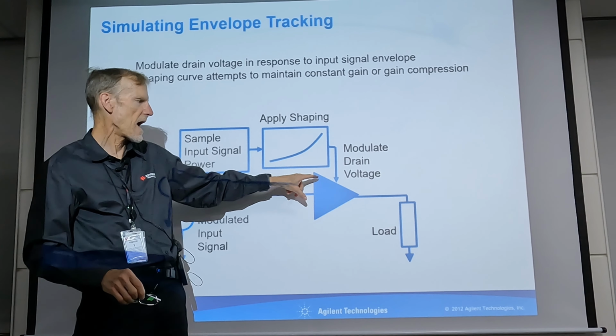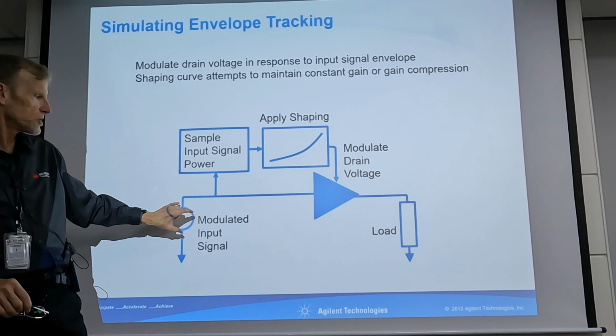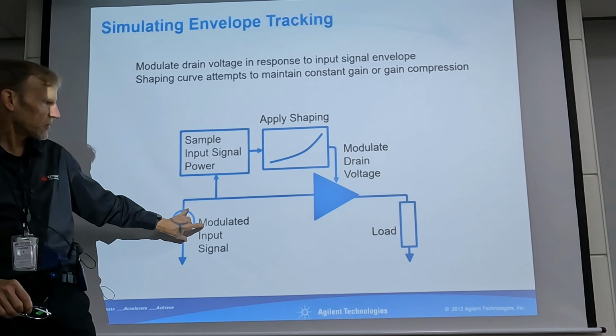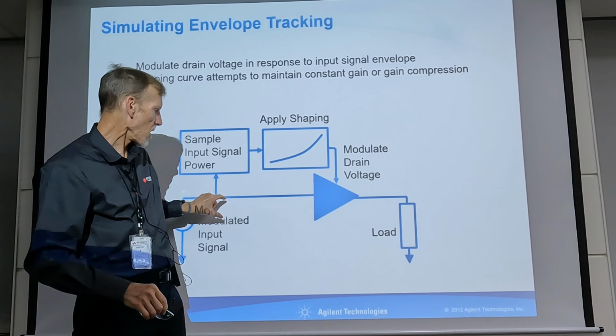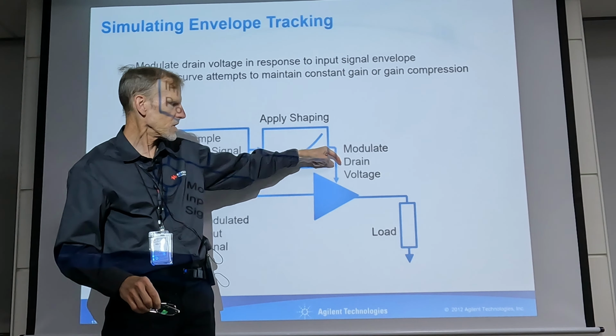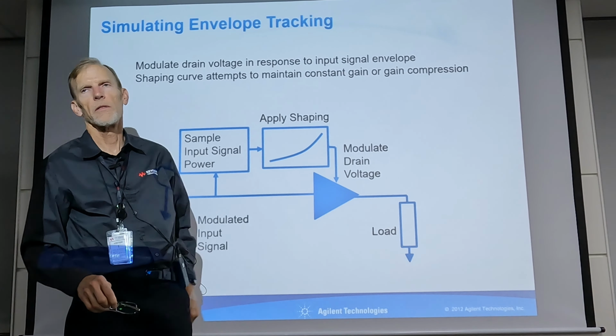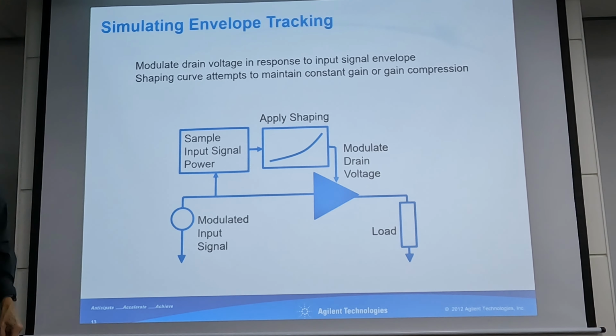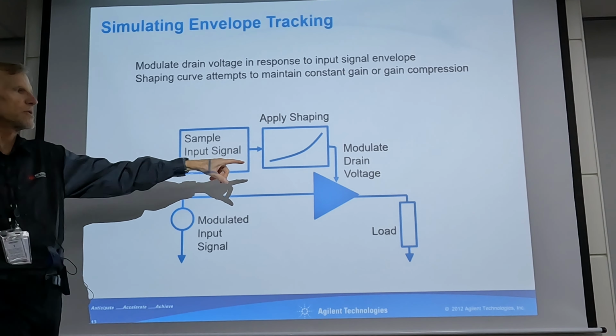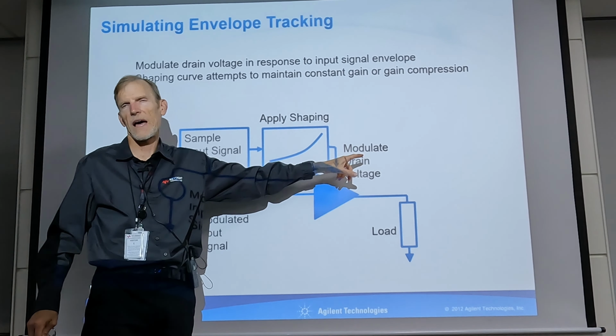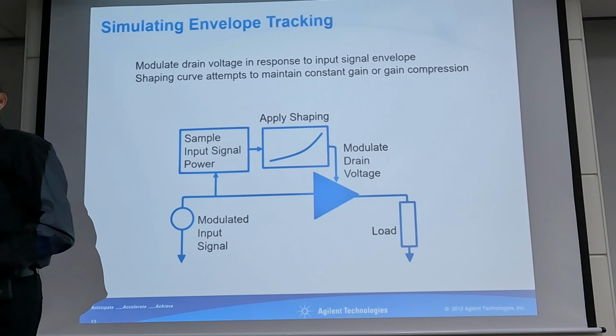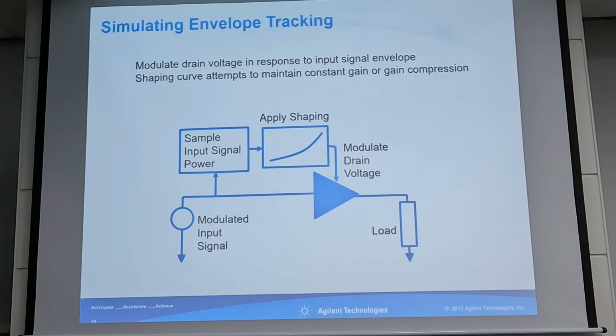So you can have a separate simulation where I have a modulated signal and a corresponding time domain signal that I'm applying to the bias, and the bias time domain signal could have distortion added to it. So that's possible to do, and I have an example of that.